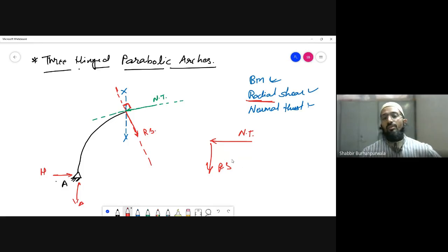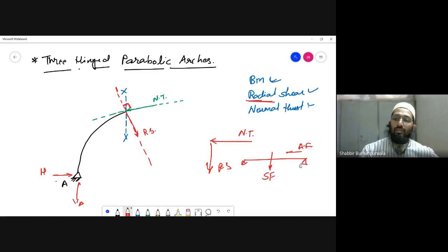आपकी जो नॉर्मल बीम होती है, बीम के अंदर आपका जो एक्शियल फोर्स होता है, ठीक है, that is always acting in the horizontal direction, and the shear force is always acting in the vertical direction. ये आपके नॉर्मल बीम के अंदर होता है, ठीक है। लेकिन यहाँ पे ऐसा नहीं है, यहाँ पे आपको हमेशा हॉरिजॉन्टल वर्टिकल नहीं मिलेगा, यहाँ पे डिपेंडिंग ऑन दी कर्वेचर इसका जो डायरेक्शन है वो चेंज होते रहेगा।